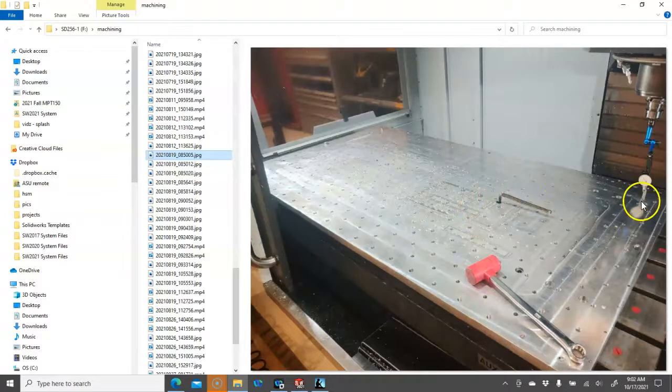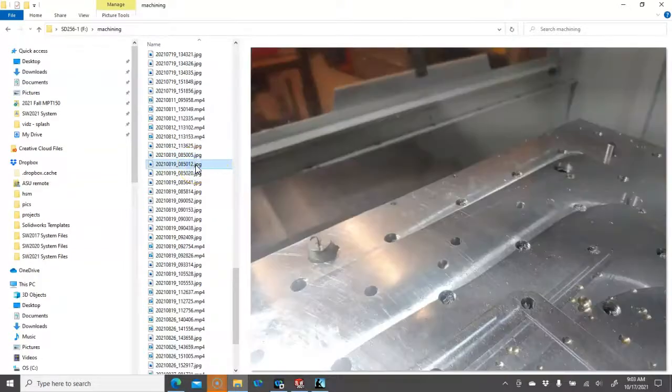So dowel pins are put in to locate the flat, large surface is our primary, and then we usually put in 2 pins across the secondary and then 1 pin for the tertiary, and that will create our datums for establishing those geometries. All right, so this gets clamped down with socketed cap screws into the T-slots on the machine table, and then you can see the pins, and I have an alignment tool that gets it pretty much within 5 or 10 thousandths to start.